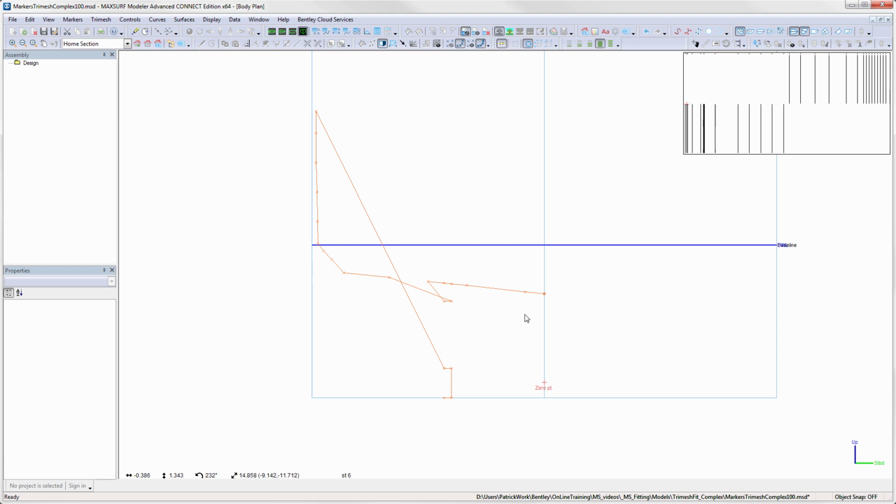So the way to sort that out is to select the markers with the shift key down in the order that they should be. It's much easier for us humans to determine the correct order. Just go all the way around, selecting all the points.